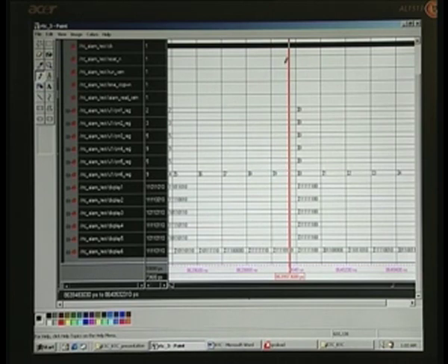So the last one is the cursor is right there on 2359, and you see that the last value was around 8.64 nanosecond, and after this you can see that all counters are made 0 here, and you can see the corresponding display. You would notice that the center G segment alone is 0, decimal point is of course 0 because we have not used decimal point, and all other segments are 1, that means it is displaying 0. This is in conformity with this 0. Second 0 stands for display 2, counter 3 for display 3, and so on.